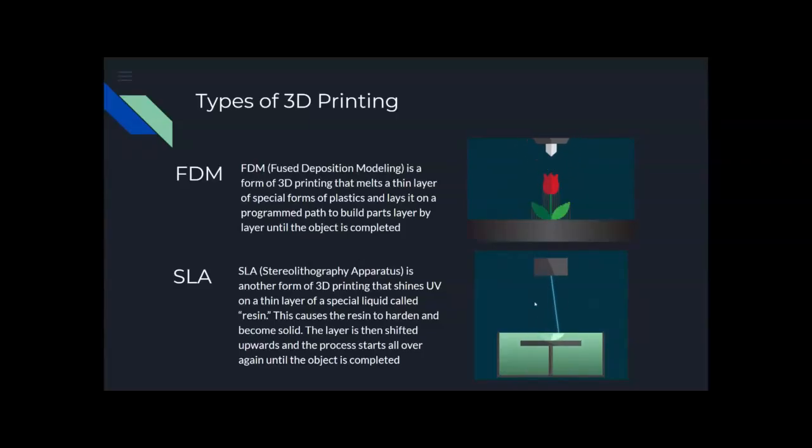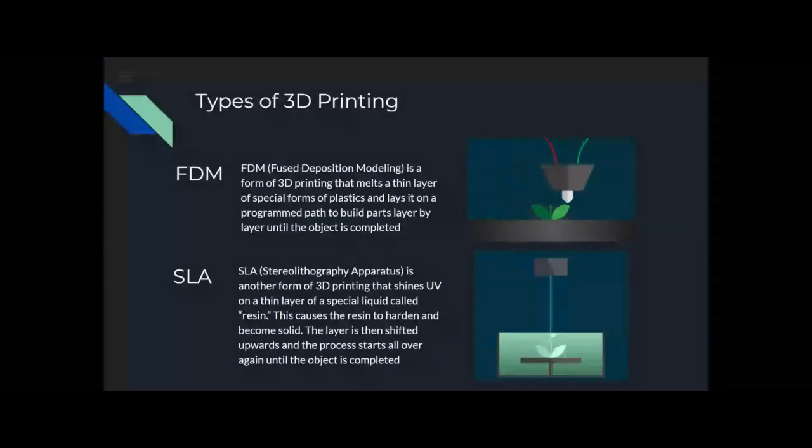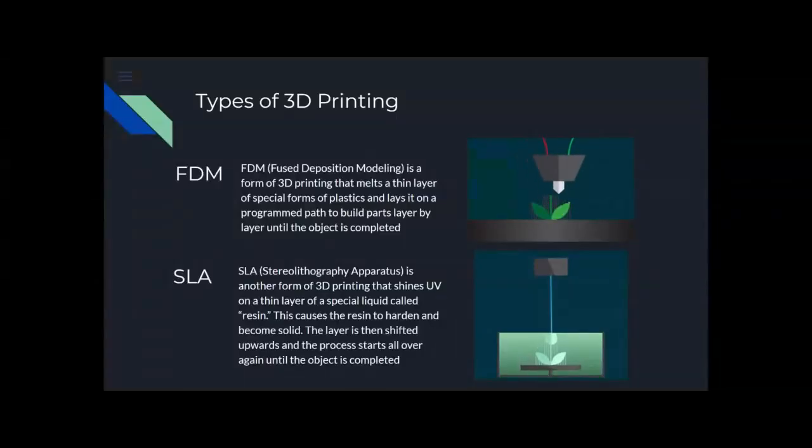This isn't exactly accurate because in a real resin printer, we no longer bounce a laser back and forth. We create a mask, which is basically just an outline that we can control. Like imagine a phone screen that you can turn on and off the pixels to be able to draw an image, and a giant UV bulb flashes the entire layer and cures it all in one go.